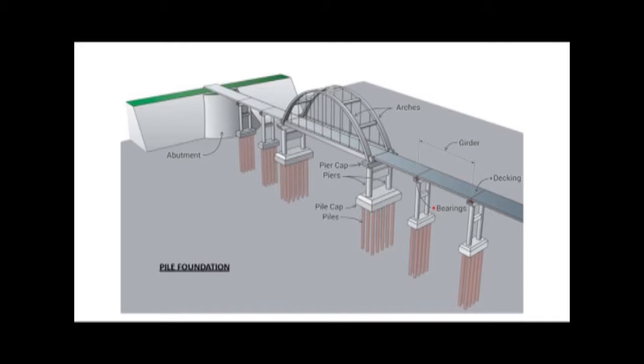For example, if the caisson goes on sinking and there's a tilt, and the tilt has occurred because of the disproportion of weight on either side of the caisson, that disproportion can be balanced by putting weight on the side on which the sinking of the caisson is less. So this is what we had for foundation. Moving on to the next slide.